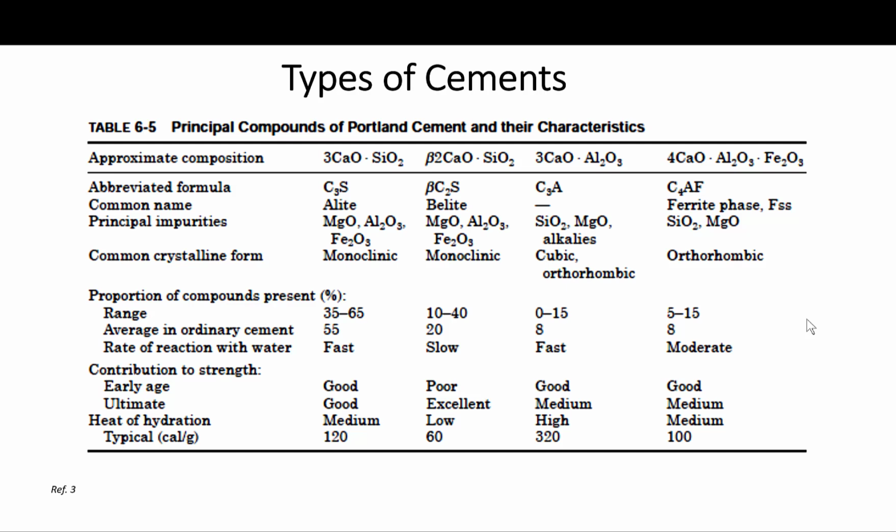Here, this table is a more comprehensive table than the one I showed earlier. It summarizes the characteristics of each of the cement phases. Okay, and here in this table also I included the common crystal structures of the phases, the impurities present in each phase, and more detailed information,